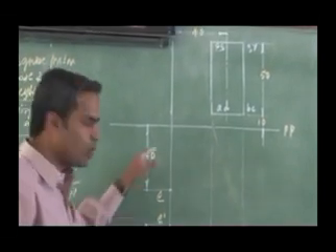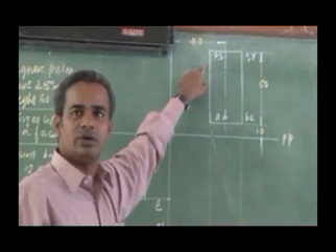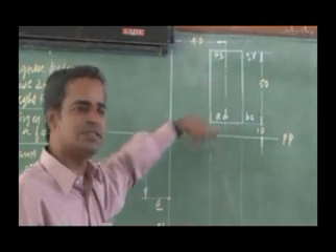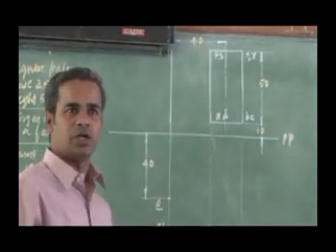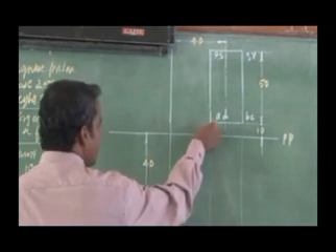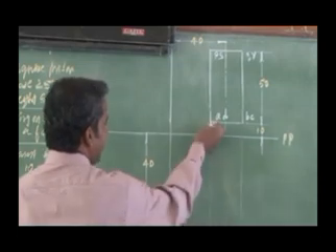So I have marked the station point in the front view and top view. This is the layout. Then you try to get the intercepts of all the corners and get the perspective view. By joining the corners to the station point in the top view, I can get the intercepts as usual.